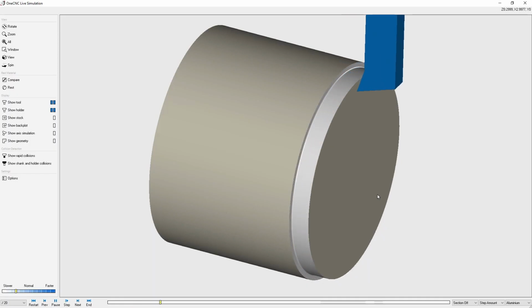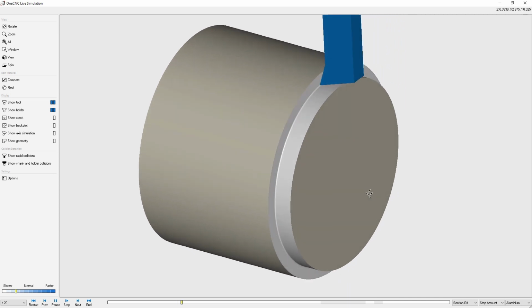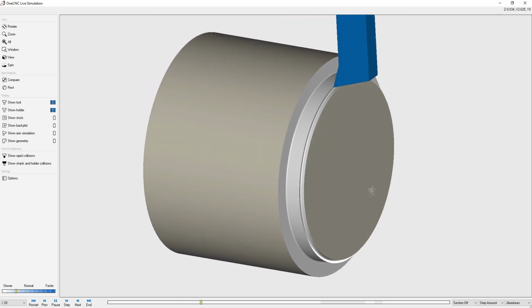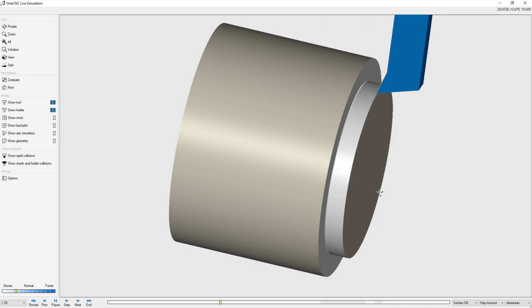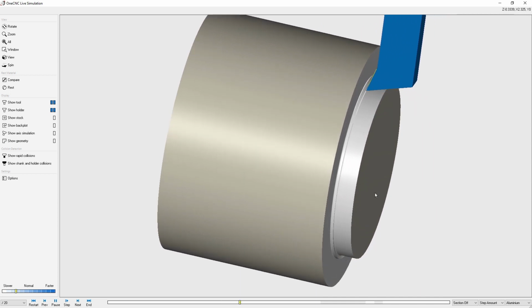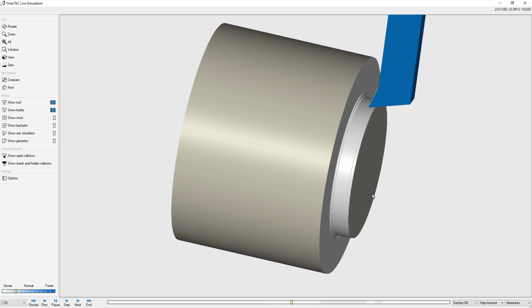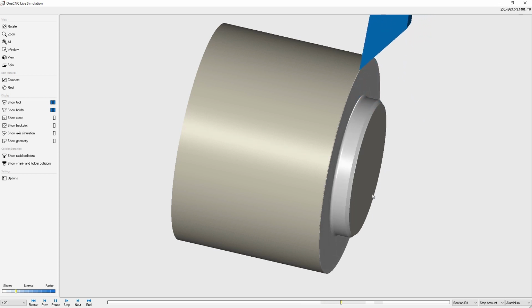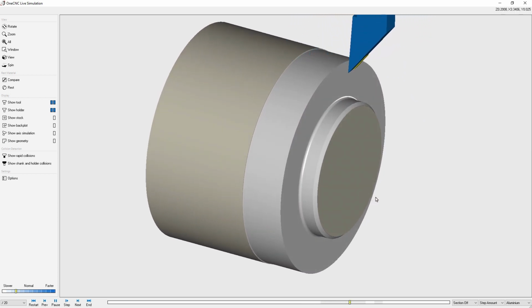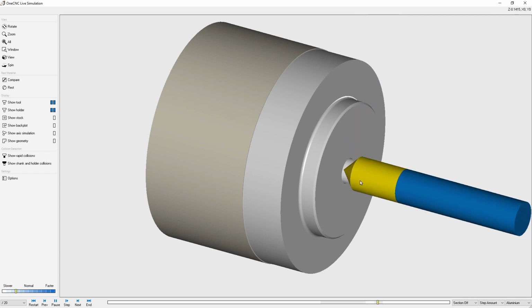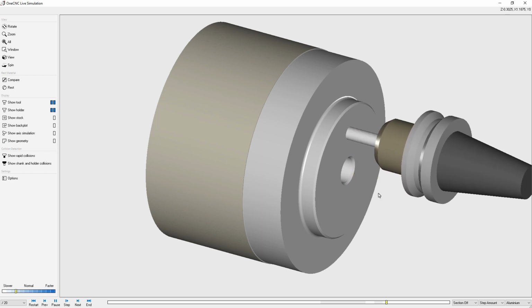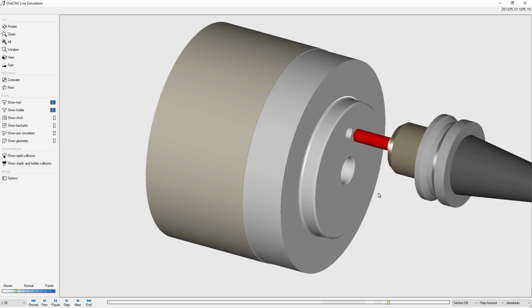All right, so we're looking at the roughing operation here. We can rotate this around if we want to. After that, we're going to perform a profile or finish operation. We're going to see that in just a second. We'll switch tools. There we go. We've got a finish tool. There's our finish pass. And then now we're performing the facing, the drilling at the center. Here's the chamfer. And now we're going to select that 3/8 diameter drill and perform our live tooling or our